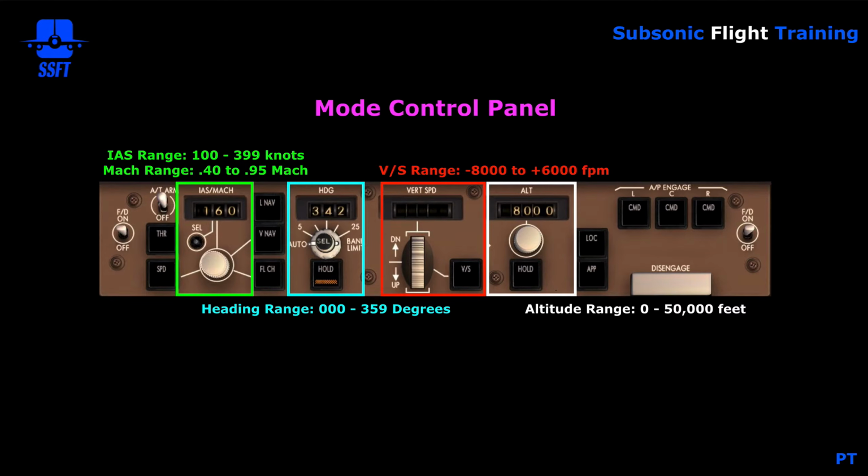Most of the time you don't notice this or see it because most of the time in the climb and the descent we're in VNAV. And when we're in VNAV, the indicated airspeed Mach window would be blank since the FMC is controlling the speed. So unless you are climbing in flight level change or a mode such as that, you would not notice the change from indicated airspeed to Mach or Mach to indicated airspeed. But in reality, the mode that's most often used in the climb and especially in the initial descent phase, closer to your cruise altitude or at a higher altitude, would be VNAV.